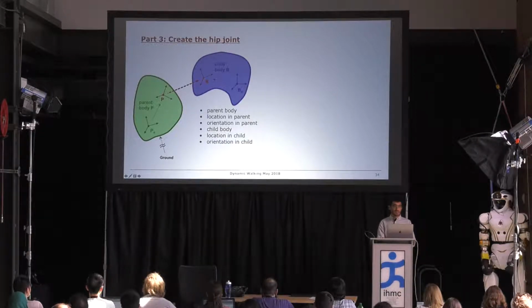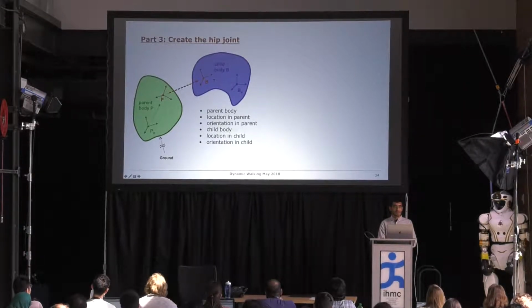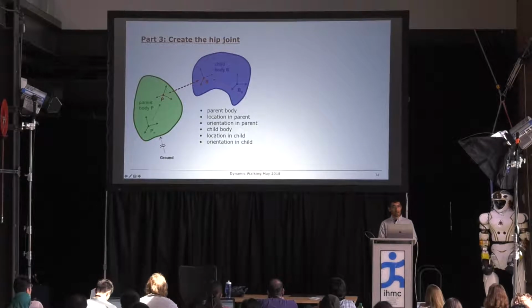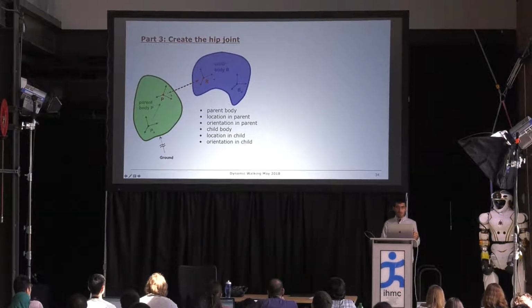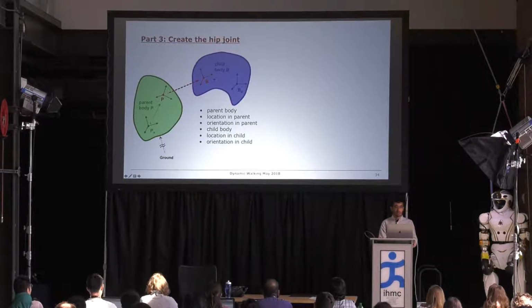So a pin joint says that the child joint frame, in red here, can rotate about the mutual z-axis of the 2 joint frames, the parent and child joint frames. To describe how the bodies move with respect to one another, we also have to specify where the joint frames are located within the body frame, and that's a constant in time transform.